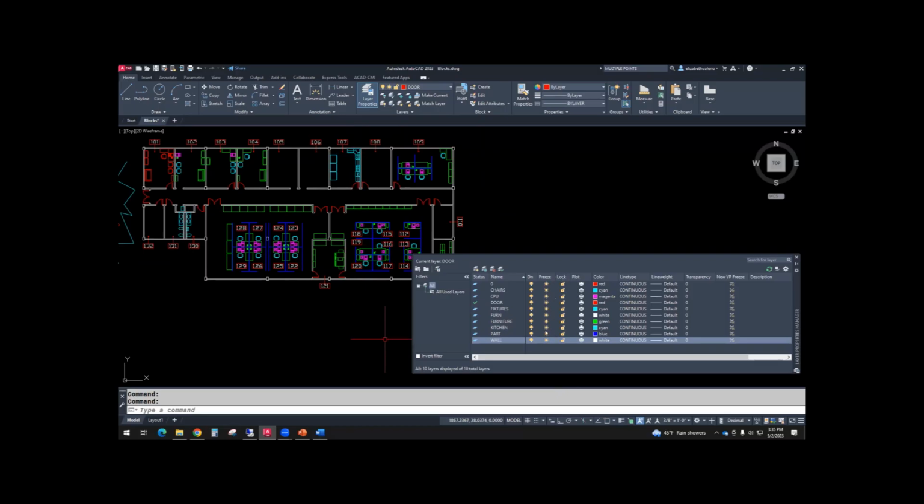Freezing things speeds up your drawing. It says, don't think about these at all. They're not deleted. You could bring them back, but just don't waste your energy thinking about these items. And then your drawing actually will speed up and run faster without those items.